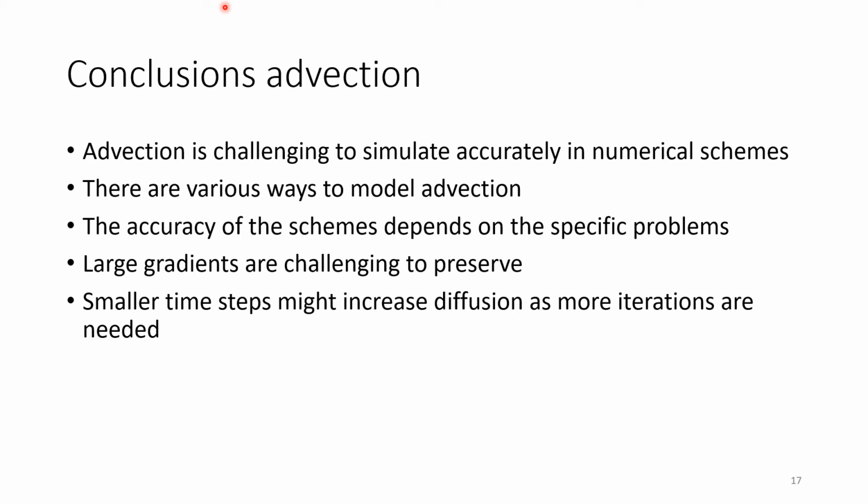If you consider introducing a tracer into the soil, there is some duration during the input. It's already diffusing as soon as you let it into the water, so you don't have this rectangular input signal that theory would always like you to have. So it's worth smoothing it, getting a realistic input signal, and that will make advection much more accurate.